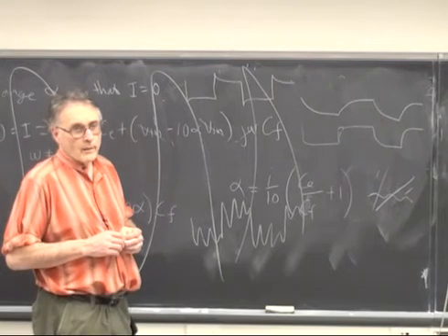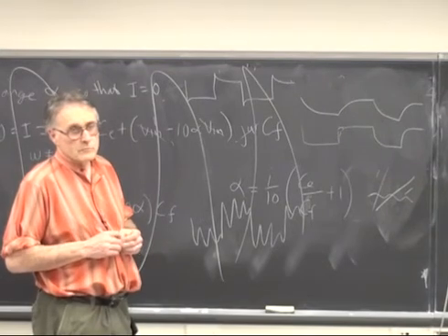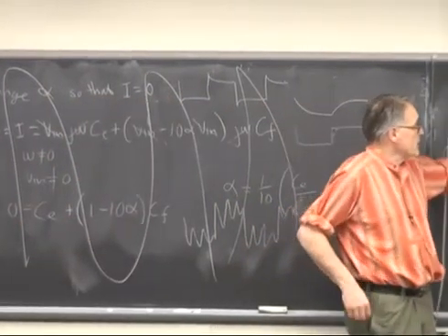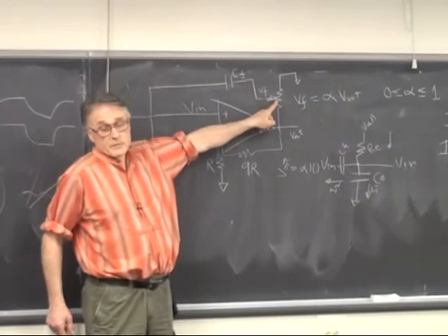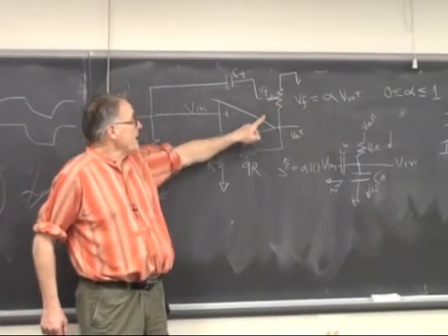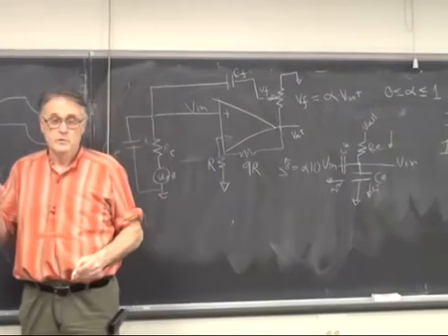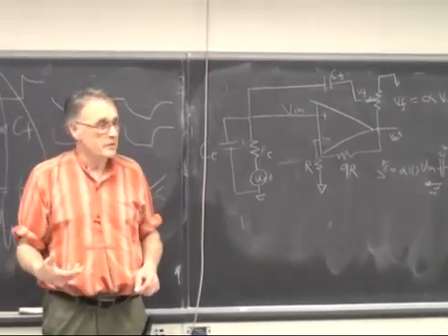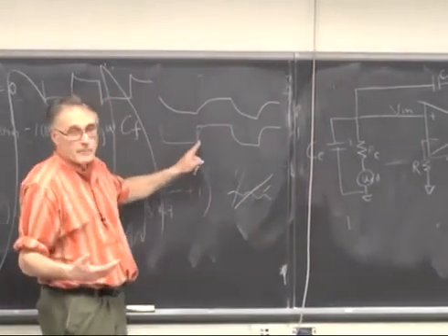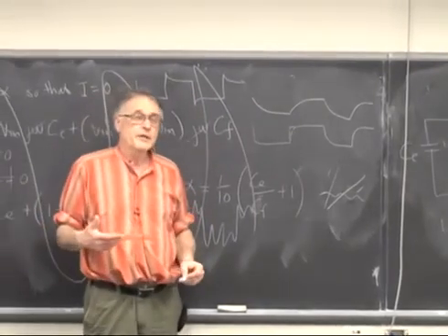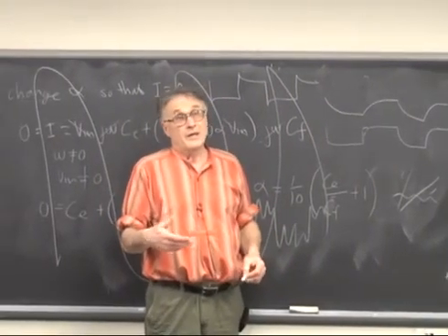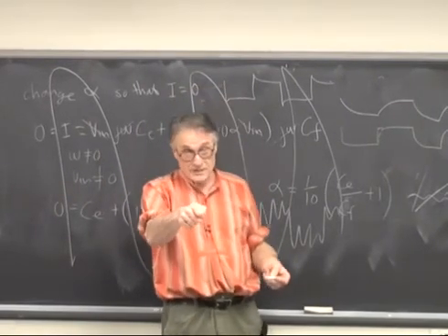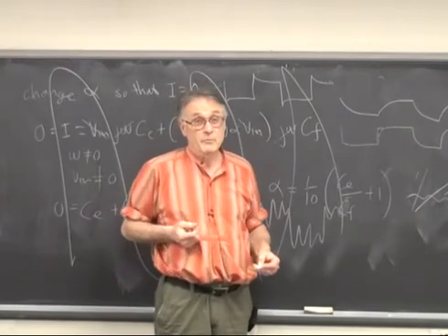Is there a sweet spot for the circuit where there's a moderate amplification and moderate bandwidth? There is a sweet spot for adjustment here, which is not a function of gain, but is a function of the feedback strength, which will give you a moderately good bandwidth and a moderately good noise. The noise increases very rapidly as you get towards 0 time constant. So if you can adjust it to the point where you get 90% of your signal and only 10% of the noise of going the next few percent, then that's where you want to be.